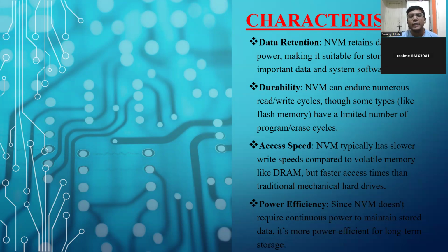Durability: NVM can endure numerous read-write cycles, though some types like flash memories have a limited number of program or erase cycles. Access speed: NVM has lower write speed as compared to volatile memory, that is DRAM, but has faster access speed than the traditional mechanical hard drive. Power efficiency: as it is not dependent on power supply, its power consumption is very effective for long-term storage.